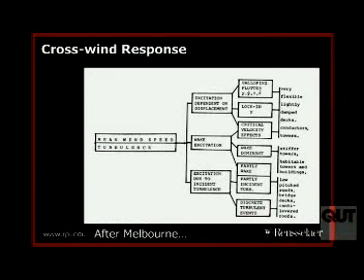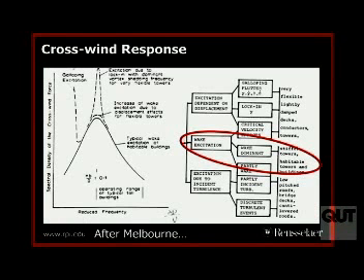And if we look at crosswind as the particular response that causes most problems, the along-wind buffeting of a structure, just the turbulent, gusty nature of the wind causing the building to have a drag-type response, that's not as significant as the crosswind response, the lateral response of a structure. And there are many different ways of causing that crosswind response. And I'm going to be typically talking about this part in the middle, wake excitation. So where the flow behind the structure is causing the problem. And again, the figure really is to talk about response versus frequency.